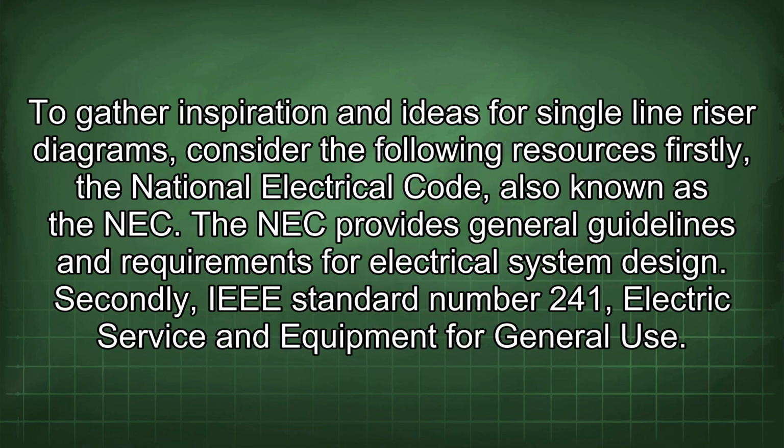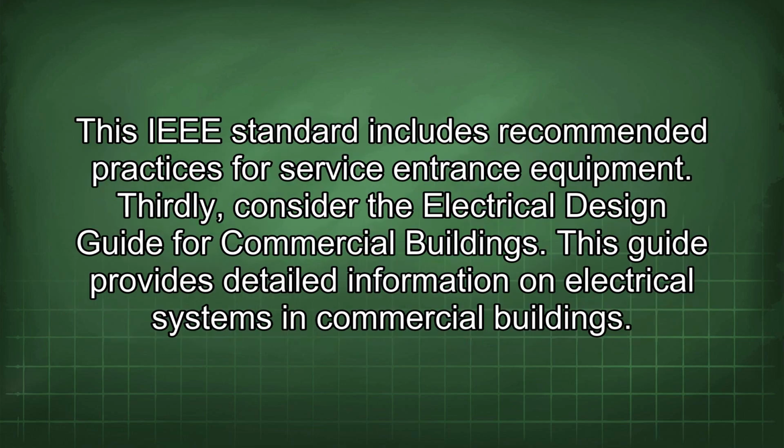To gather inspiration and ideas for single-line riser diagrams, consider the following resources. Firstly, the National Electrical Code, also known as the NEC. The NEC provides general guidelines and requirements for electrical system design. Secondly, IEEE Standard 241, Electric Service and Equipment for General Use. This IEEE standard includes recommended practices for service entrance equipment.